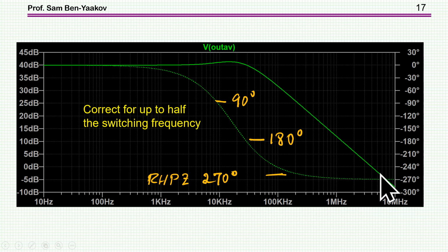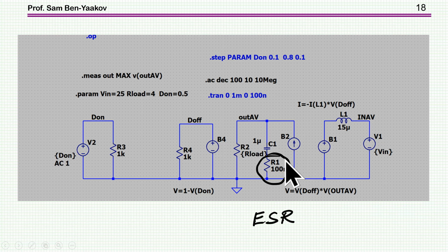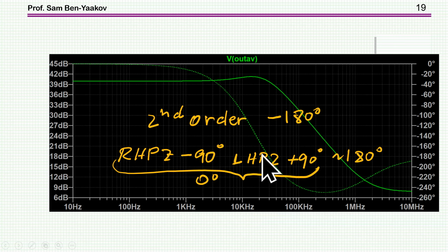Now, I'm adding here an ESR to the capacitor. This adds a 0, a left half plane 0, and here it is.